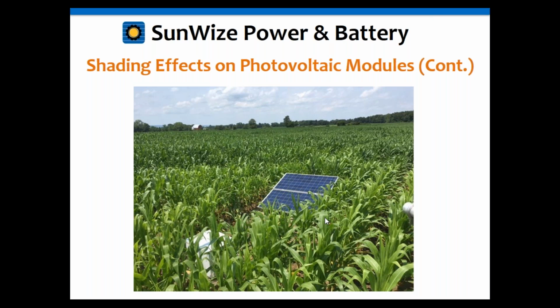When you go out to site sometimes, this is also important with maintenance, just do a quick inspection. If you see vegetation that has grown up, that can be a problem. You need to trim it back or cut it down or whatever it is to make certain it is not shading the solar array, even just a cell. And that's why I get back to, again, you don't want any shading whatsoever, because just shading a single cell can render that module or even that entire string output to 0.